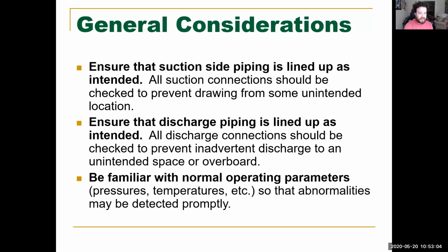All right, and then be familiar with normal operating parameters. Pressures, temperatures, so abnormalities can be detected promptly. Rule of thumb with motors, guys, motors should not be running any hotter than the ability to put your hand on it. All right, if you burn your hand basically from a motor, something's very wrong if it's running that hot. But you should be able to put your hand on the motor and it should be running at a nice, good temperature. All right.